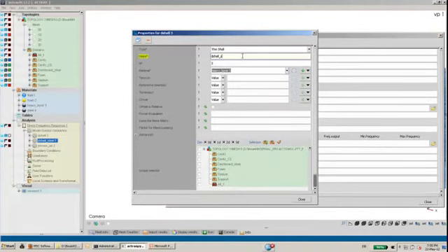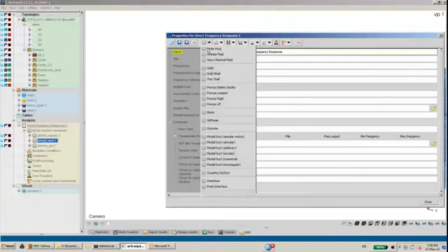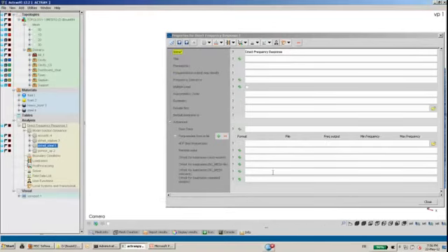Here I will rename it, and here again I need to enter the thickness, and the thickness of my septum is decided to be 3 millimeters. And again I need to select the right domain, which is here the septum. Okay, and last but not least, as a physical component, I need to create the acoustic fluid for the cavity, to refer it to the valid fluid material and assign it to the cavity element set.